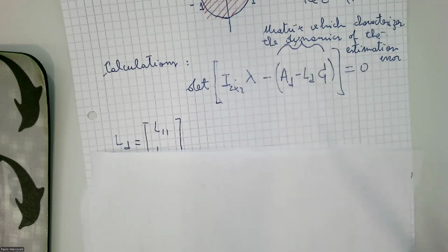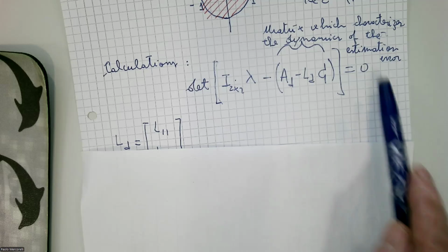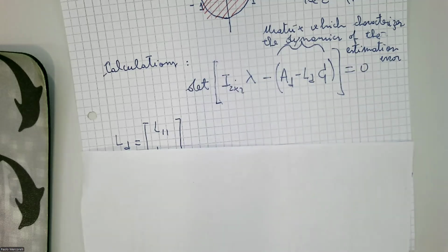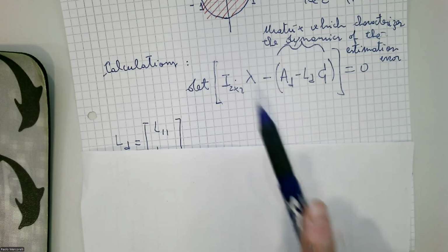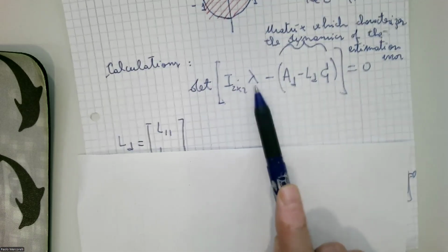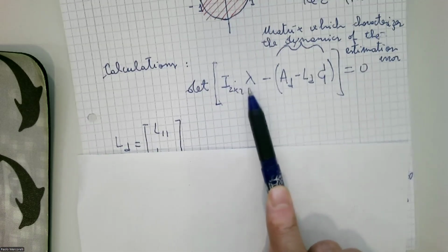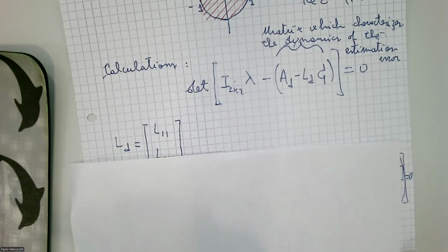But here the problem is a little bit different. This is the condition. A little bit different because LD is unknown. And in this sense it is easier, because if LD is unknown, I can place the eigenvalue really inside the circle. Why? Because I can fix my 2 eigenvalues in discrete form, considering what I told you until now.